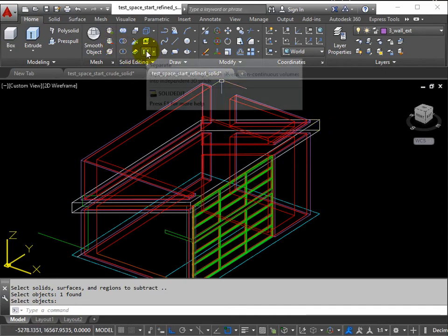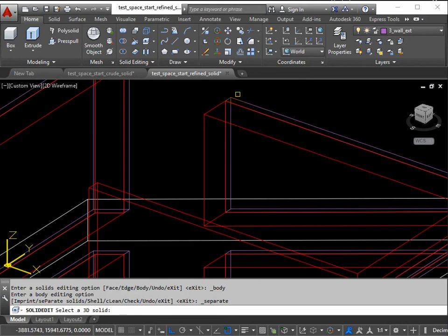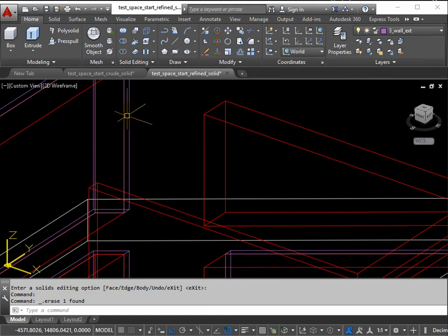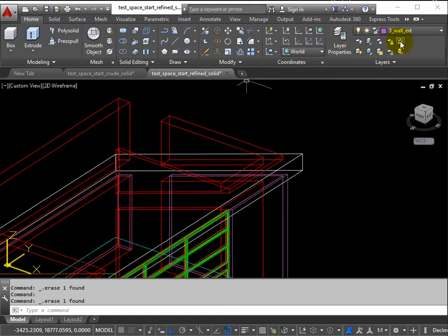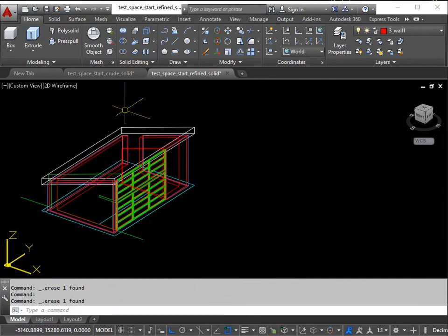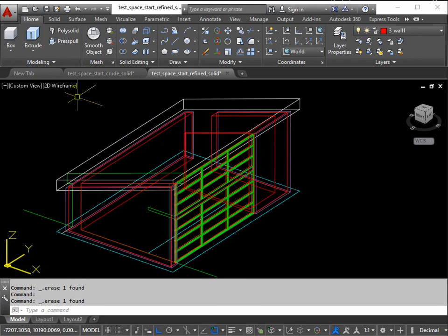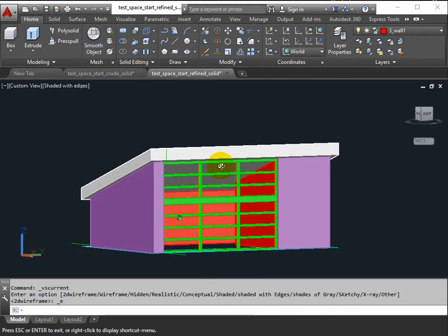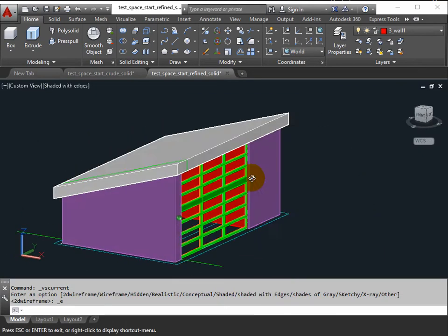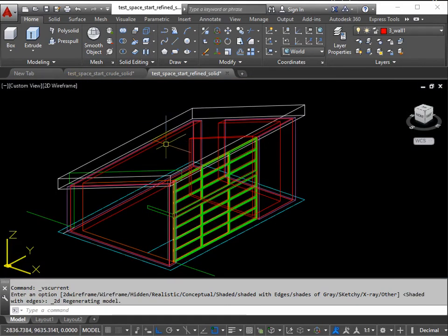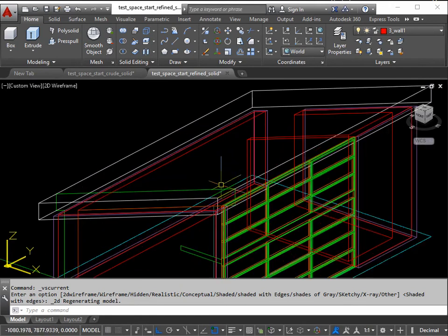We've then got to do the separating again. We're just doing everything twice effectively. So we separate and then delete. Make the red the current layer, separate, a couple of returns, and then delete. So the model's getting the definition that we had in the 3D face model. You can still see we've got control over inside and outside materials, but it's just a little bit trickier and a bit more care required in the setting up.